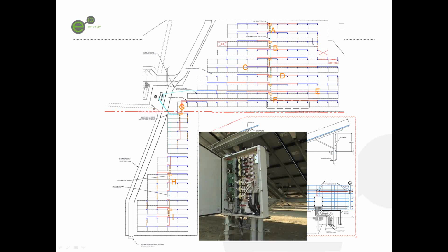As you can see here, these are the outputs that are going back to the inverter. In this case, we ganged 4 500 MCM aluminum lines for each vCom and ran those back to the inverter. You can also see here the input channels for each one of the trunk lines coming back from the array. So this makes it a little more visual as to what's actually happening and what that looks like when you get out to the field. You can also see in here the 125 amp fuses, which are lined up down here. In this case, we have 6 125 amp fuses, and then that power is all ganged up into these two sets of contacts in the box.